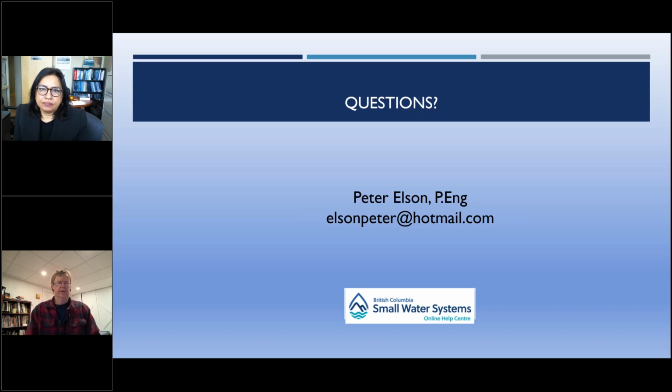So you have a good sense of that. And again, I wouldn't be opposed to writing that on your spreadsheet as well. In fact, you can have multiple spreadsheets if it makes it easier, for example, to focus on pump issues, chlorinator issues, that kind of thing. Just so you have, for instance, two clipboards, so you make sure you have enough space to easily write down all those numbers. But yeah, I would always recommend that a level sensor is put into a well for sure.